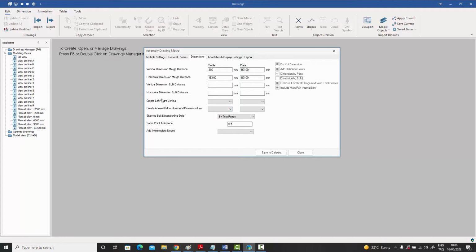So it will say that the gusset plate starts at 3000 and ends at whatever, some number. The other way of doing this, now this is obviously possible, but another way would be that if that gusset plate had any holes in it, then instead of giving the dimension of the edge of the gusset plate, it will give the dimension of the first bolt and the second bolt, let's say, of the gusset plate.